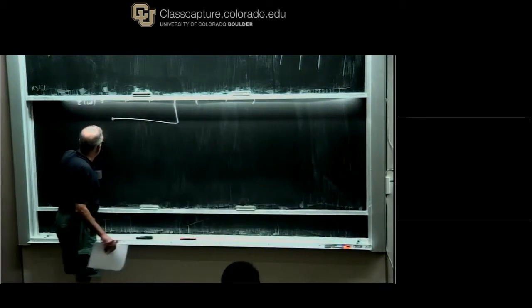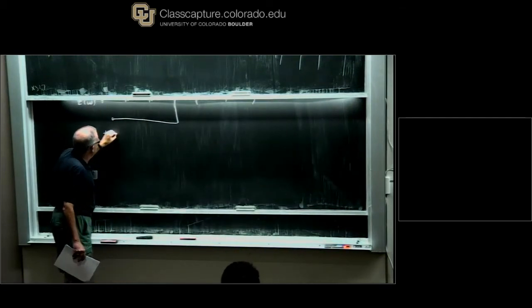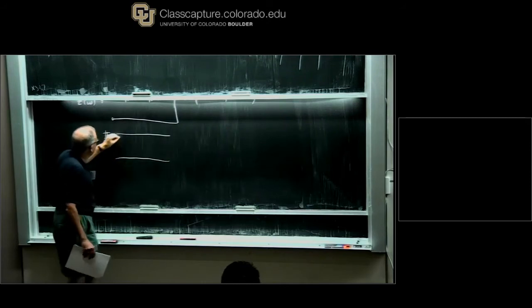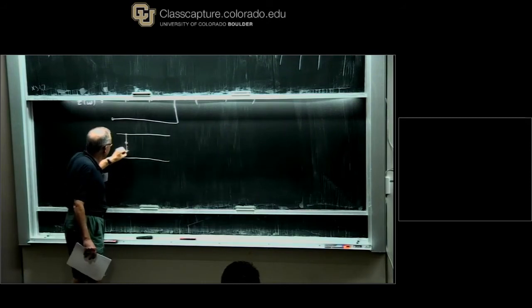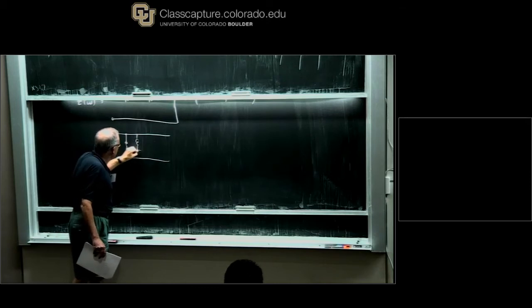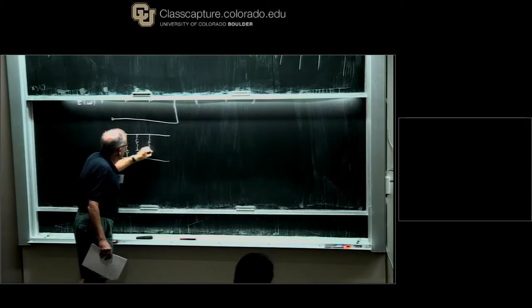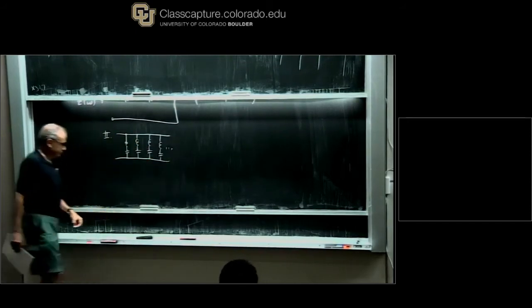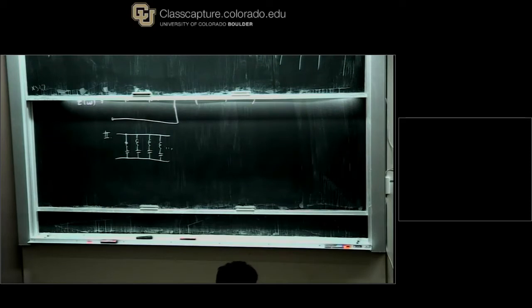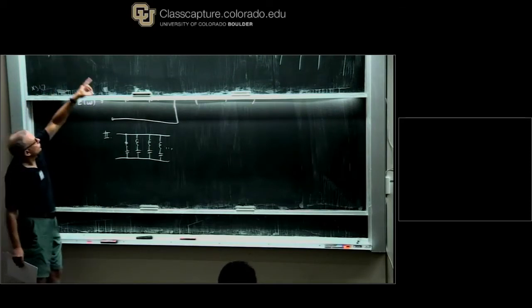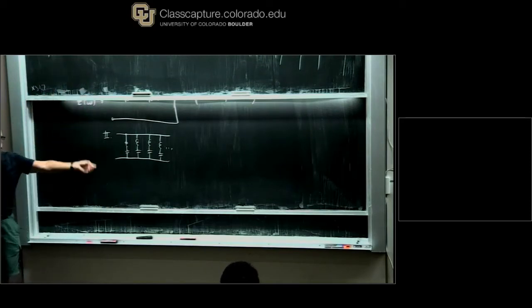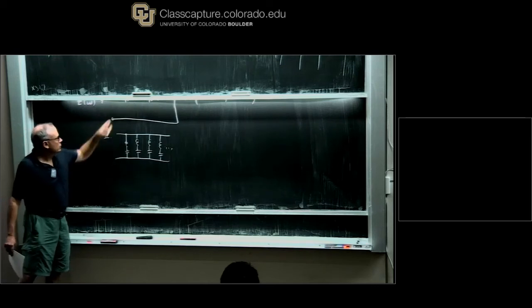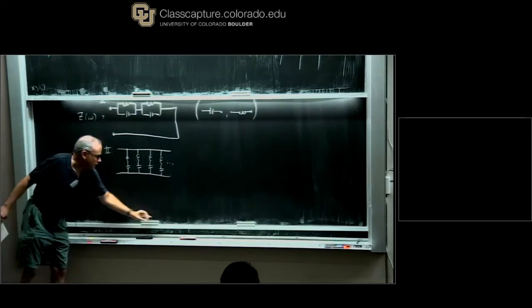Oops, that loses that. Okay, I'll bring it back though. Foster 2 is a more kind of parallel representation. But this too, once you've decided on this topology of the circuit, is also unique. So no matter how complex the structure is, distributed conductors and dielectrics here and there, as long as it's lossless, it can always be represented by one of these two canonical forms.